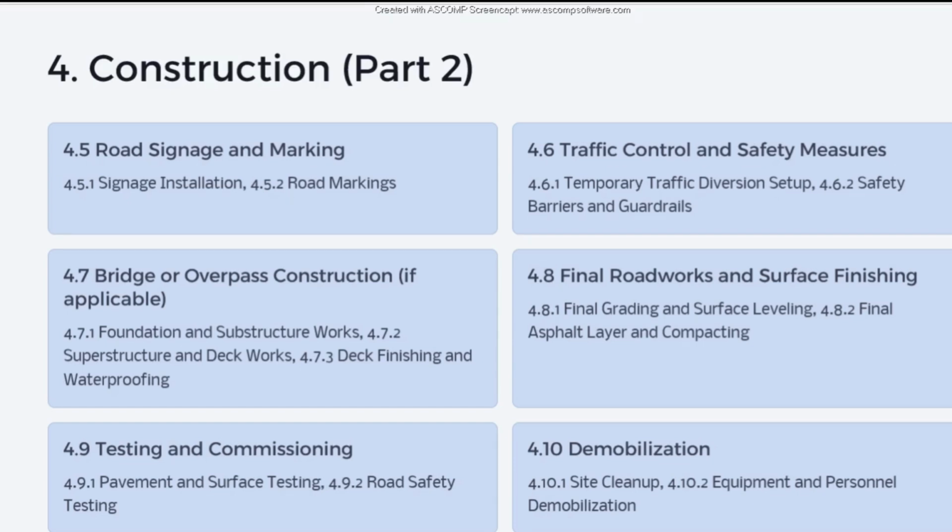No, you could have added one layer with the same thickness of two layers, but it is meant on purpose to be two layers because when you add your first layer you have a variance in dimensions, variance in thickness. There could be more tolerance in the dimensions, differences between the drawings and the construction site.